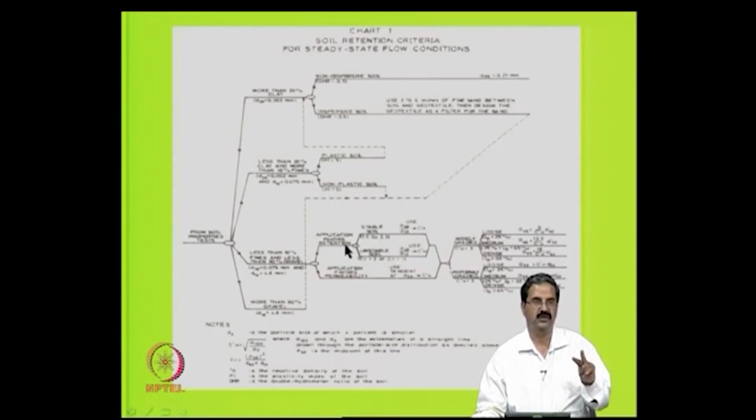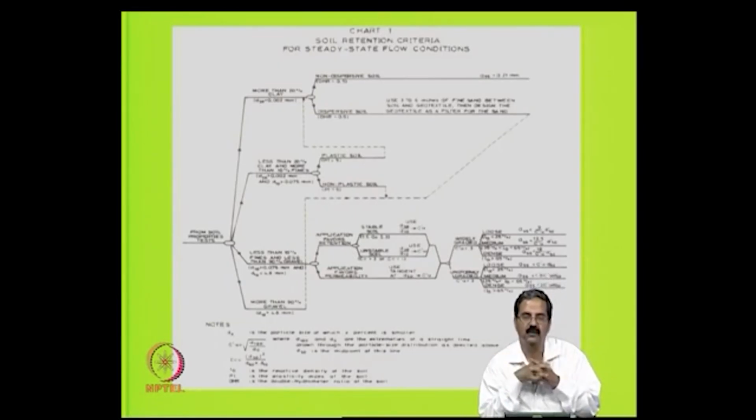You have to choose. There are two things here: one is the flow of water, and the other is soil retention. From the point of soil retention you need small pores, but in terms of the permeability criteria you want big pores. They are both contradictory requirements, so based on the grain size distribution only, you want to get everything again.